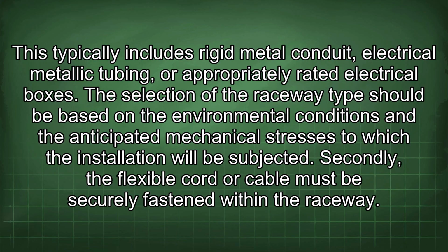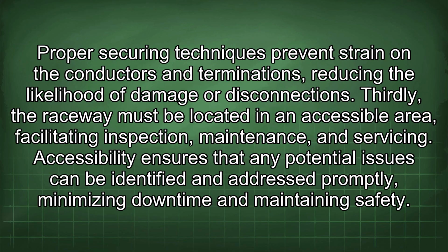Secondly, the flexible cord or cable must be securely fastened within the raceway. Proper securing techniques prevent strain on the conductors and terminations, reducing the likelihood of damage or disconnections. Thirdly, the raceway must be located in an accessible area, facilitating inspection, maintenance, and servicing. Accessibility ensures that any potential issues can be identified and addressed promptly, minimizing downtime and maintaining safety.